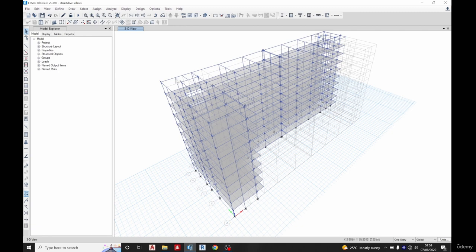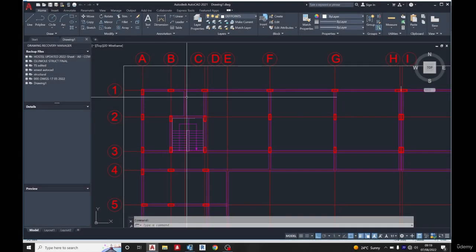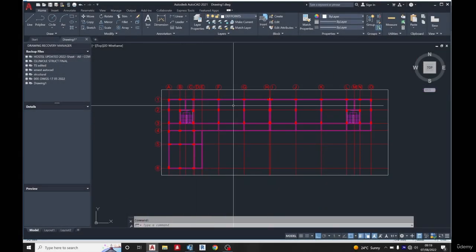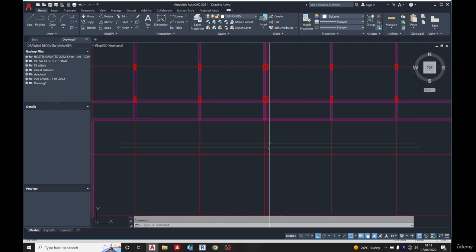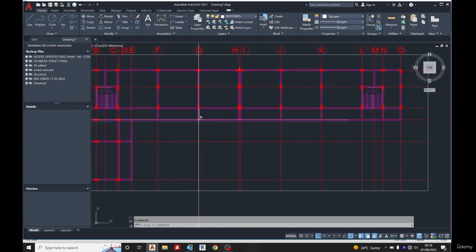So what we are going to be doing is placing shear walls in some strategic positions to reduce this drifting. So we'll be placing our shear walls in strategic positions. And remember, I told us in the previous video that there is a shear wall along this place for lift, but I removed this purposely for the case to check if we need the normal shear wall or we'll just place a normal concrete masonry wall, put columns and beams with masonry to fill the shear wall.